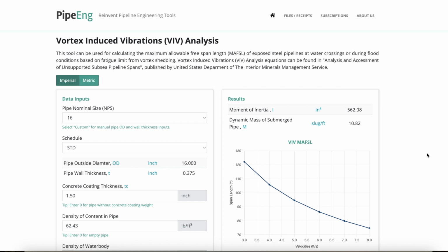When we analyze the real risk of a pipeline at exposed rivers, it's very common that pipeline operators need to prioritize the locations to repair, because you might find hundreds of exposed pipe locations for your pipelines, but you only have a limited budget for a given year. So it's paramount to really run the pipe stress analysis, and do this vortex-induced vibration analysis, to see if your pipe is really at high risk or your pipeline has a little bit more time for its lifespan.